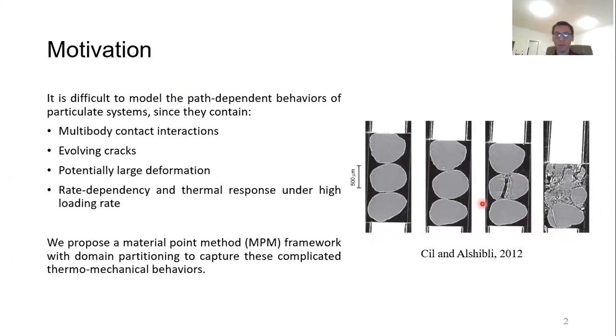As we can see in this particle crushing experiments, we need to consider multi-body contact interactions, and we may have evolving crack. And while fragmentation, those materials can undergo very large deformation, and the entire experiment may be rate dependent, and we need to consider a thermal response under high loading rate. So we propose a material point method framework with domain partitioning to capture all of these complicated thermomechanical behaviors.